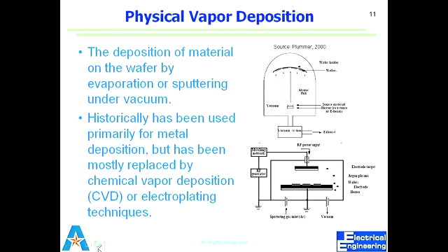So we don't lose any material to the walls of the chamber. What we get is essentially straight from that pure source to the wafer uninterrupted. Now the growth of film is a factor of many other things. Right now we're talking about when you pump down the chamber, essentially you're increasing mean free path. So they would get to the wafer unimpeded.